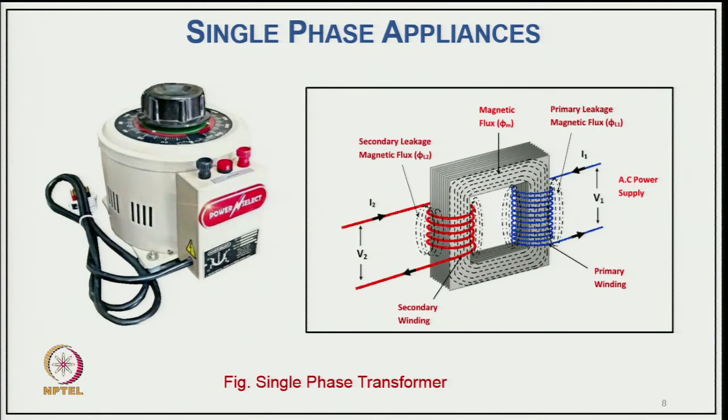Of course, as we discussed, we have different kinds of transformers in single phase also. You might have an auto transformer, which is used only for changing the voltage level without isolation, but the cost is reduced because you do not have 2 windings, only one set of winding. But we also have the transformer used for several purposes. One purpose is providing isolation or a large voltage level difference. Another is that you can have multiple outputs: with the help of a transformer you can connect a single source to one winding, and then have several secondaries which can provide power to different isolated loads. In many situations we require such conditions even for single phase transformers.